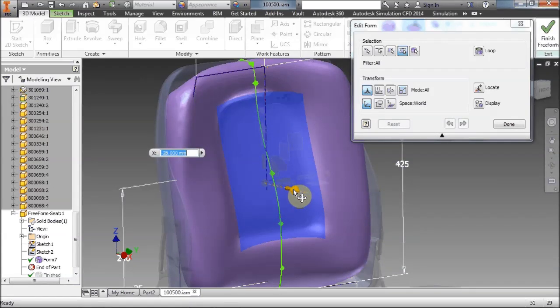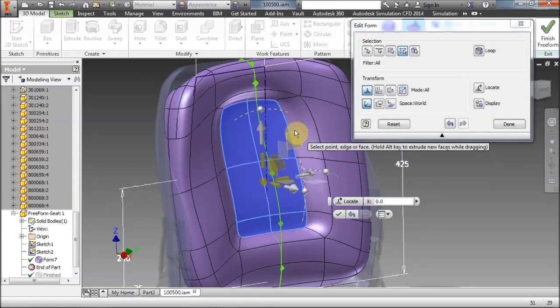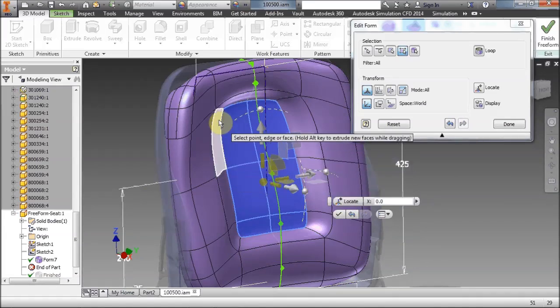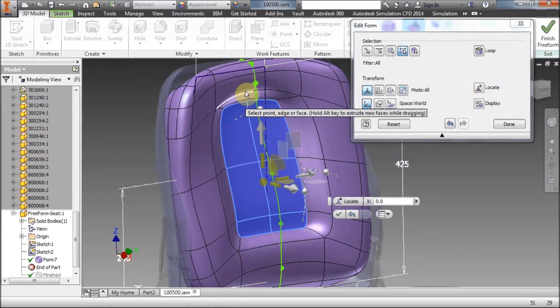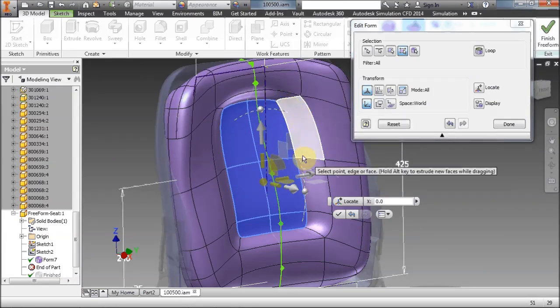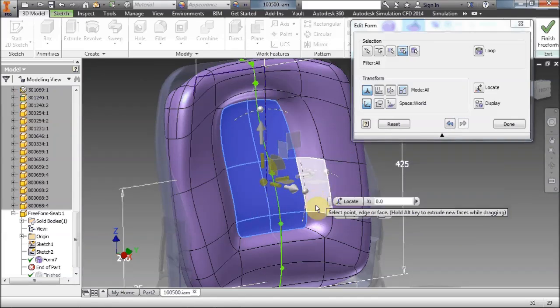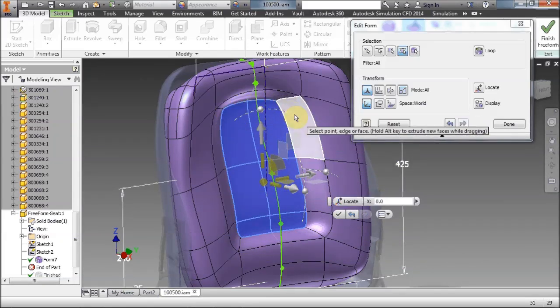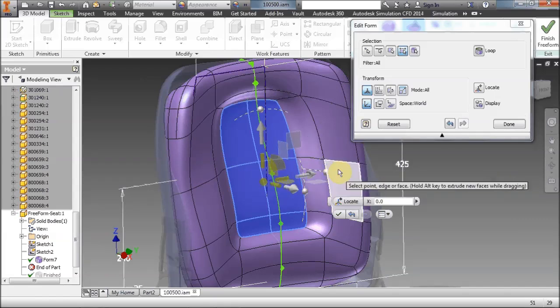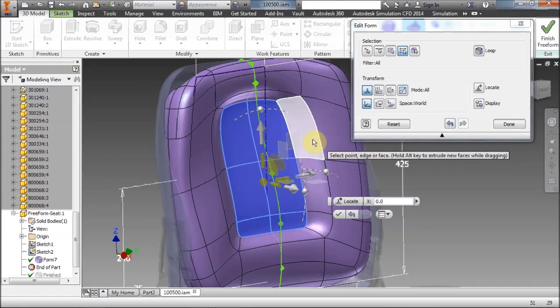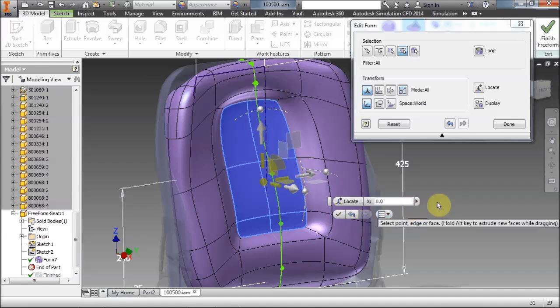Now the extrude option will do the freeform modeling of extrude as we know in Inventor, whereby instead it will give us a much coarser or larger draft, if you like, around the edges here to give us an extrusion, so we can push these faces in but still give us tangential patches all the way around the edges here to give us a smooth link, if you like, between these patches as they transverse across to this area here in the center.